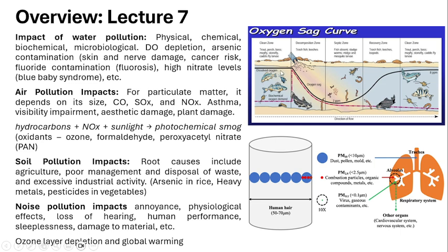And here, if you see, the water body is divided into different zones. The first zone is the clean zone. Clean zone means the amount of dissolved oxygen in the water is very good, so the water is saturated with DO. And then there comes the decomposition zone. The level of dissolved oxygen is now decreasing, because of which the number of living organisms is reduced. And then in the septic zone, it is completely depleted. It is much less than the critical limit, so no living organism can live in this septic zone except some microorganisms.